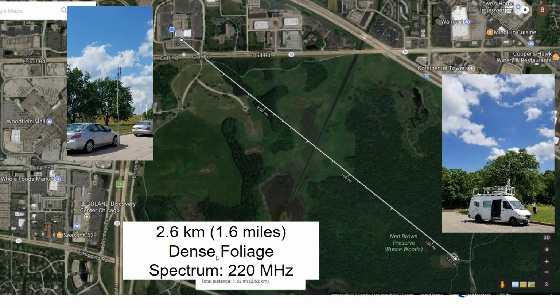Some of the results, and we used everything from 200 kilohertz channels down to 12.5 kilohertz channels, and showed the propagation through that dense foliage going about 1.6 miles, and that was still achieving the full modulation by connecting through that with just a Yagi antenna at both ends. So I think John might have mentioned that you can do different channelization in the AMTS band. We do support up to 200 kilohertz channels in that band with the cnReach radio.